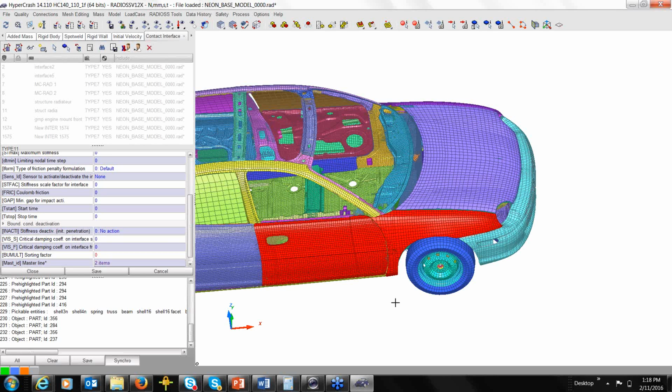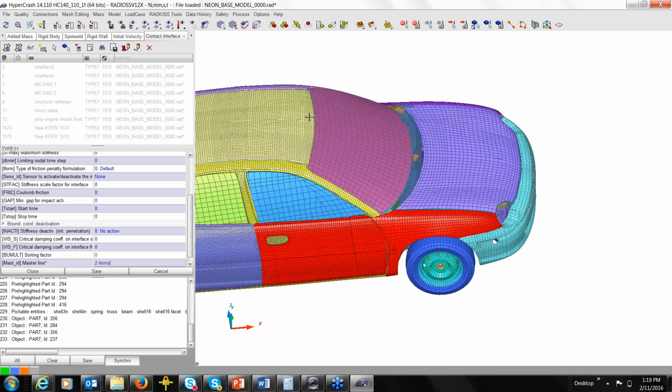The segment surface is the 2-node, 2D. So you have to create all the faces of those 3D elements, the segment surface, for the solver to manage the contact. But if you build this in HyperCrash, you don't need to create any skin. Let me just show you a demo.